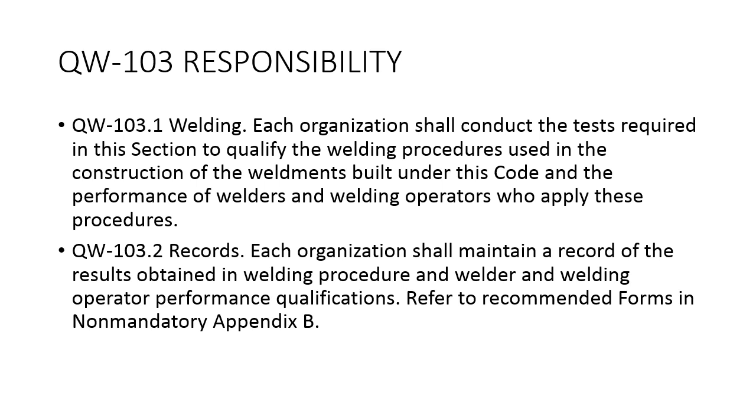Get yourself a file cabinet. Put everything in there when you're building your WPS or your PQRs. You put everything together, you make yourself a little documentation packet, so then if somebody audits you, you can break it out and say, okay, this is when we did the testing, this is when we tested our welders, this is what we've got going on. It's just telling you basically you got to keep documentation.